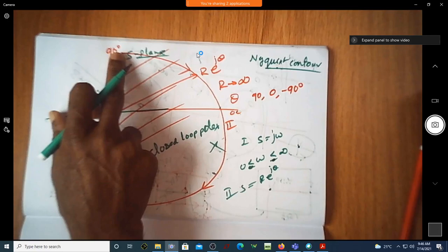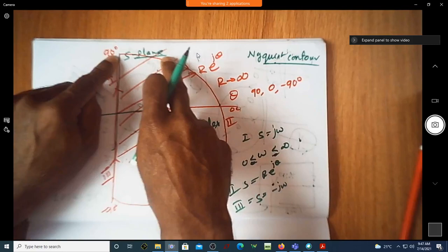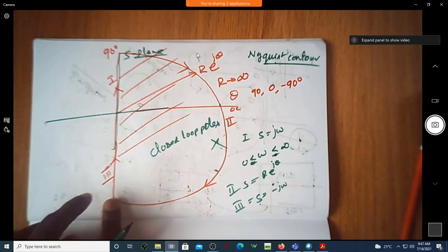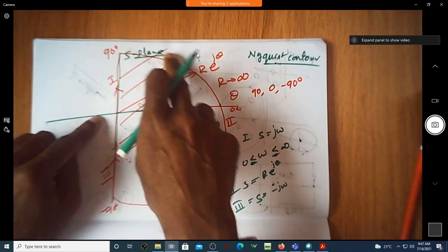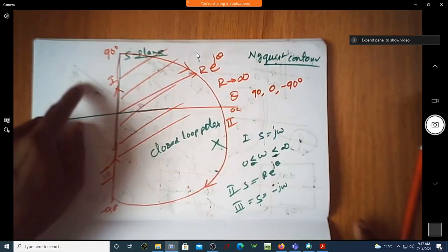So it's like a relay. In this relay, there are only three runners. First runner will start from 0, that is j0. He'll go up to j infinity. Correct? Yes, sir. He hands over the baton to the second person, who runs from infinity at an angle of 90 degrees all the way down to this. He has completed his running. And he'll hand over the baton to the third runner. He runs from minus infinity to 0, of course, minus j infinity to 0. Is the relay over? Is the relay completed? Yes, sir. Meaning that we have a closed contour. Correct?